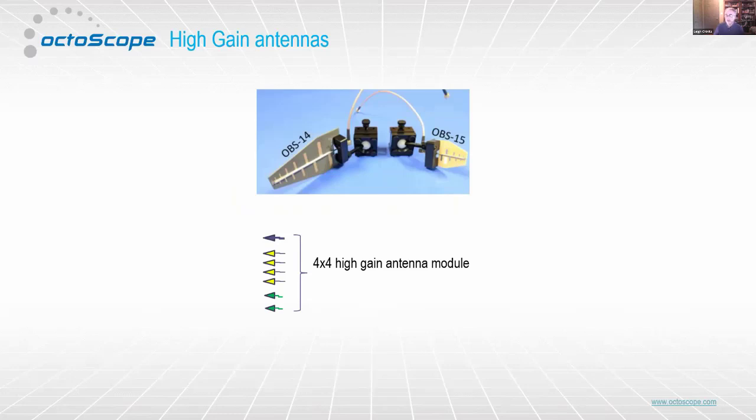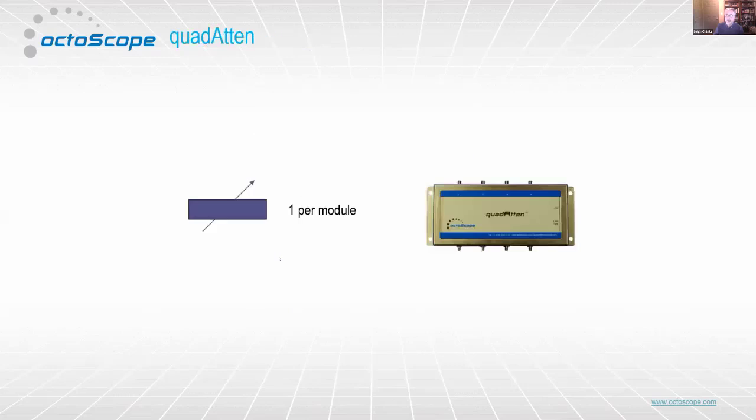The key part of our testbeds is that they're over-the-air testbeds. So the device under test is almost always using an over-the-air connection, talking to some of these test antennas. And so when you look at the logical diagram, you see these little arrows. That's what that represents. As the RF energy is moved back and forth between the chambers, it goes through programmable attenuators, and they look like this thing on the right, but they look like this blue box with the arrow through it on the left.